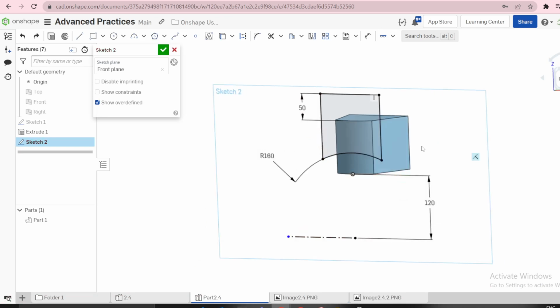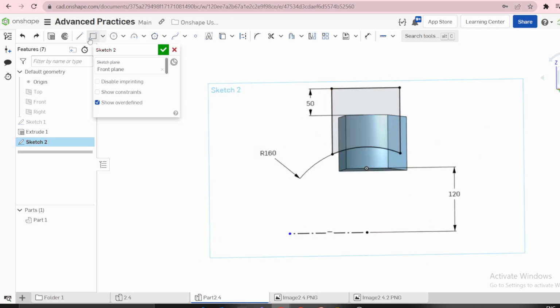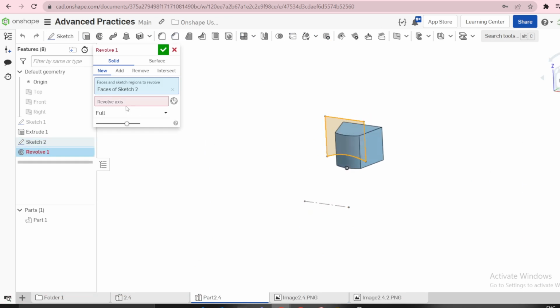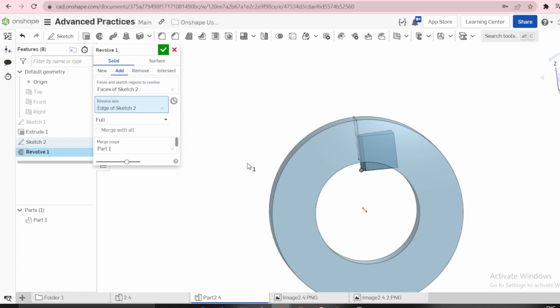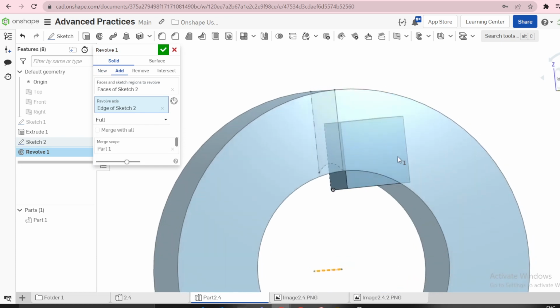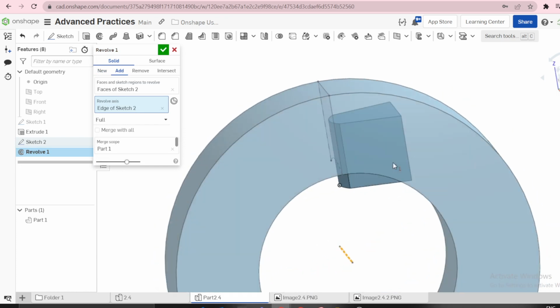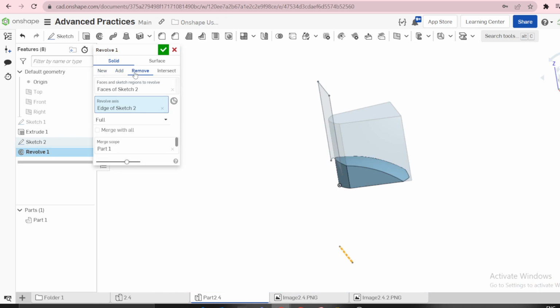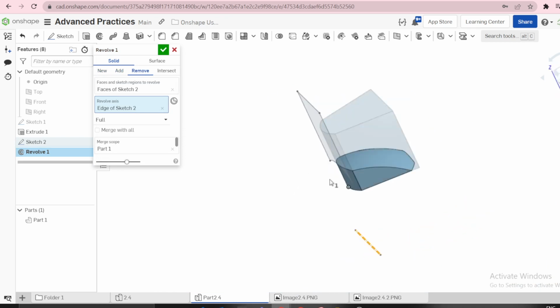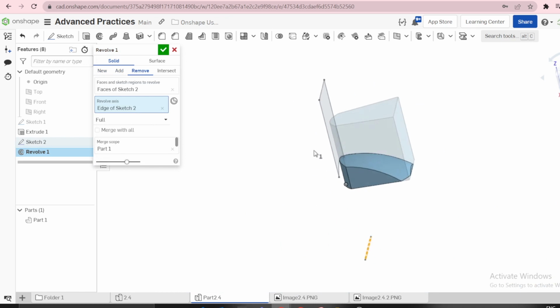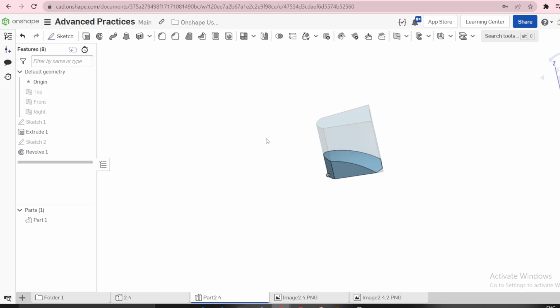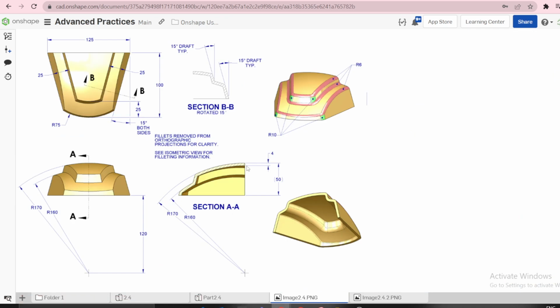Okay. I want to revolve my sketch onto this line, therefore revolve axis to be this. Okay. You can see like that. Then I need to remove. Something happens. You can see what has happened, meaning that we have used a wrong plane. Because you can see now this difference from this, meaning the revolve has to start from the back.